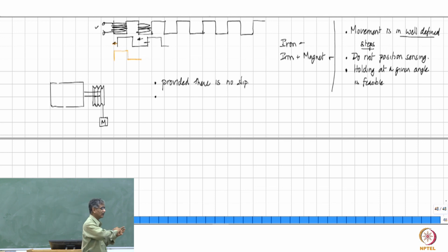So you will have a certain overshoot, and when it overshoots, because you have energized this, it will tend to snap back into alignment, and therefore it will tend to rotate back, and when it rotates back, there will be an undershoot, right? So when you attempt to energize this and move it into a particular location, the actual movement of the rotor angle, suppose it was here, and you want to move it to the next angle, you will have something like this.